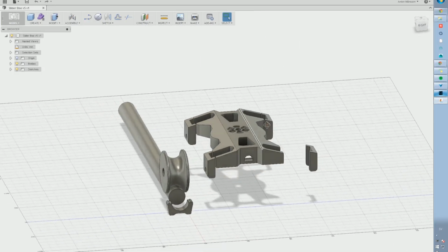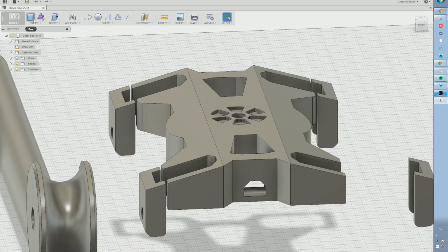So this software is really good. You have the different modes here in the software. So you have modeling, which is solid modeling, patches to create shapes or surface models instead of solid models. You have rendering. You can do some easy animation if you want to show how something's supposed to work. Simulation, where you can simulate pressure and things like that. And CAM, so you can prepare for milling, creating different paths for your CNC machines and so on. You can actually see how the machines will work.